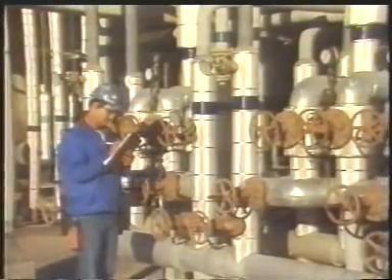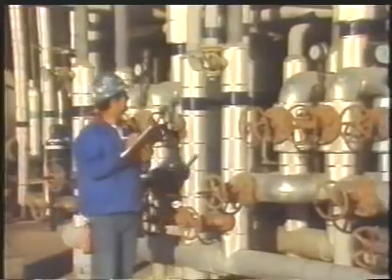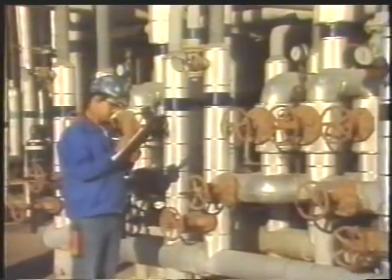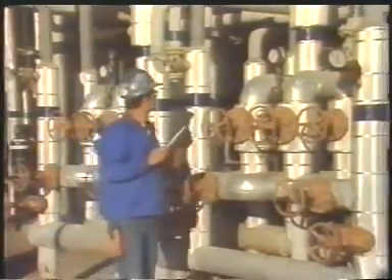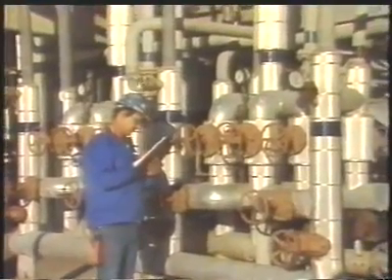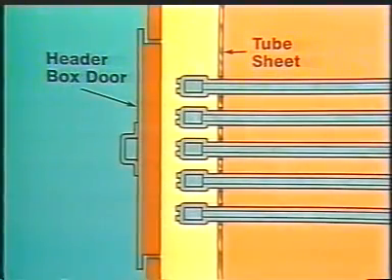While it's possible to monitor much of the furnace activity from the control room, it's also necessary to physically inspect the furnace during operation. The header box houses the tube end fittings outside the main case of the furnace. Smoke coming from the header box indicates a tube leak. Another indication of this problem would be smoke rising out of the stack.